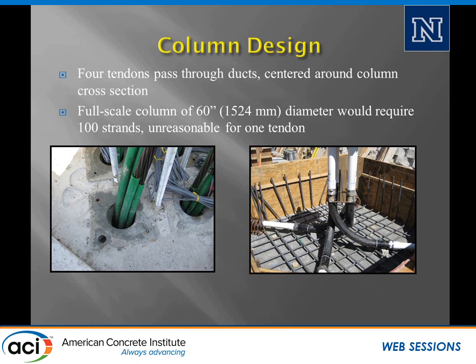Another thing that we did is that the tendons that we used were actually coated in plastic with grease in them. So again, trying to add a layer of protection. So it's not just typical post-tensioning strand or a Dywidag bar. It's actual strand that's coated with grease with the plastic sheath. So this would be the same thing that you would use in a slab. Okay, so we're actually increasing the protection over this slab.